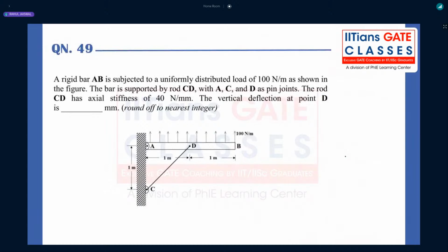Okay, so basically most of you might be stuck with this question. I was expecting it to be a little bit on the higher side, but we already solved this particular problem in our classroom. There was no difficulty because they have clearly mentioned the rigid bar, right? So this problem does not belong to bending, and no bending will be considered in case of the beam, because they clearly mentioned it should be rigid. It will just be rotated with the angle theta. There will not be any relative deformation permitted in the beam, right?